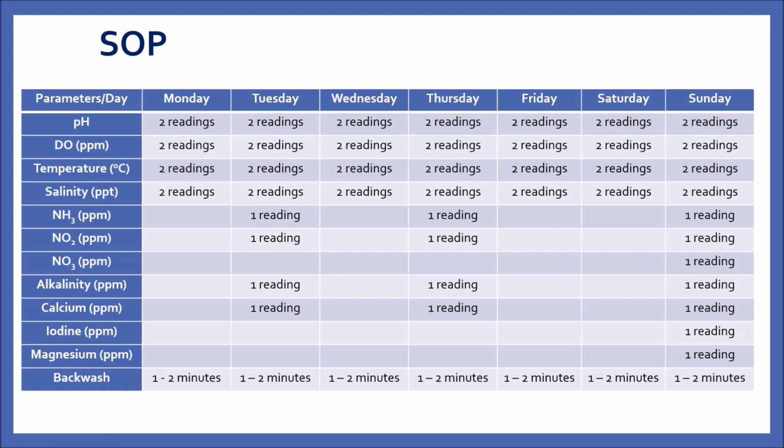For alkalinity, we are utilizing a titration kit. We can take it every other day, as well as calcium. Magnesium and iodine are not key values and you can take them every week. For the sand filter, we're recommending backwashing every day for 1 to 2 minutes.